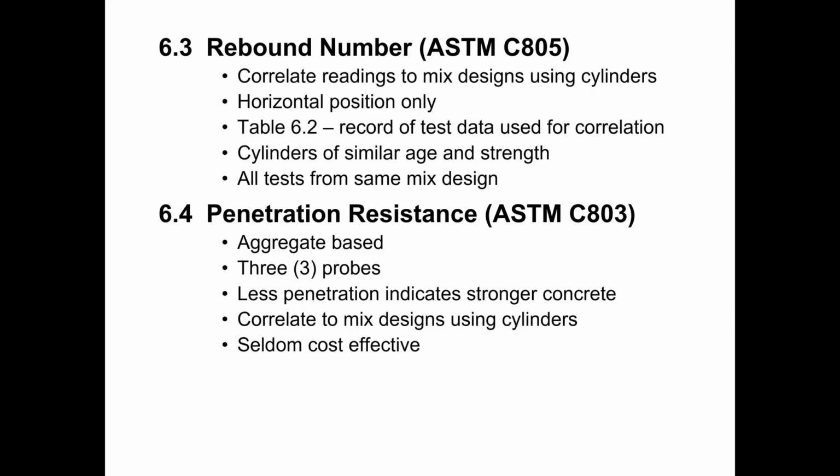So if we do this multiple times over a period of time, over a range of concrete strengths, then that will help us to develop a correlation curve for the penetration resistance test. This is also referred to as a Windsor probe test, so maybe you've heard of the Windsor probe test.